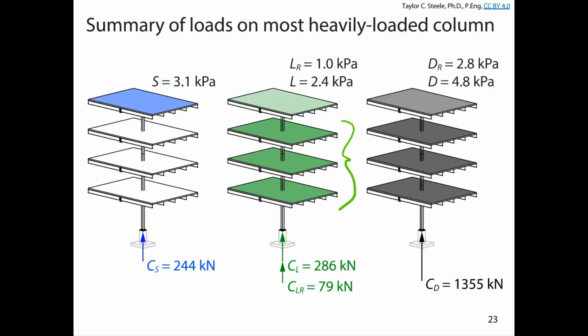What stands out to me anyway is the biggest one. Which one's the biggest? Dead load, by a reasonable amount, right? So the dead load is always going to be a significant load acting on these kinds of columns. For the most part, the structure is 70% responsible just to stand there by itself, and maybe 30% responsible for carrying some other loads like snow and live loads, okay? So that's for the bottom column. We're going to stop there for the example.